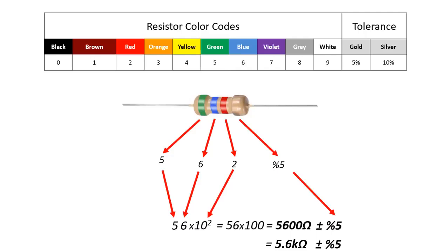Any resistor of over 1,000 ohms is typically shortened using the letter K. For instance, 1,000 would be 1 kiloohm, 3,900 ohms would be translated to 3.9 kiloohms, and 470,000 ohms would become 470 kiloohms. Values of ohms over 1,000,000 are represented using the letter M. In this case, 1,000,000 ohms would become 1 megohm.